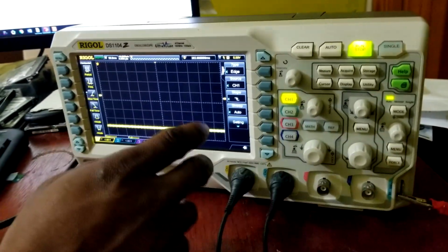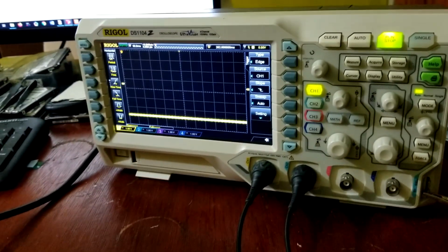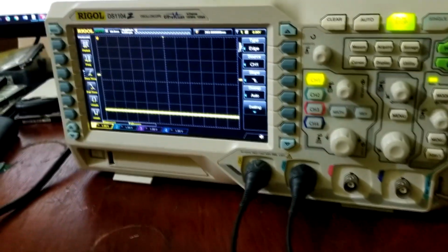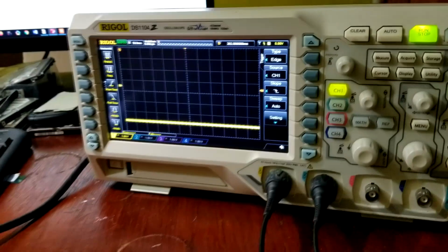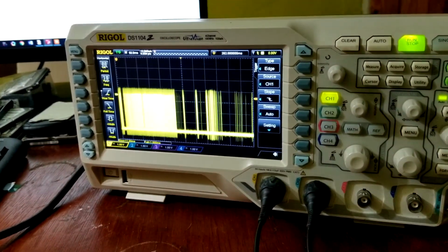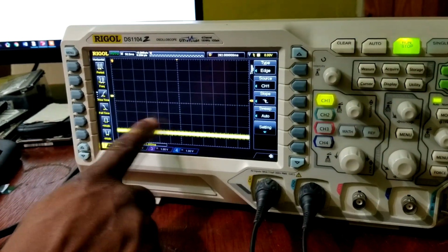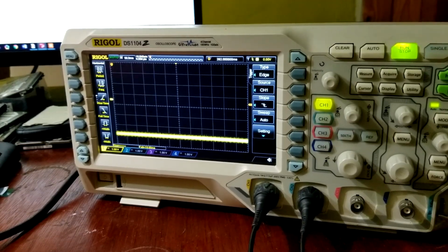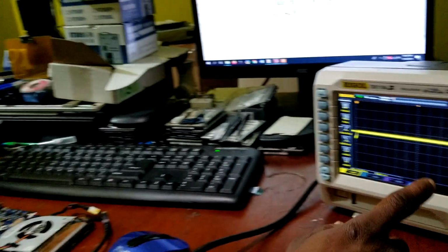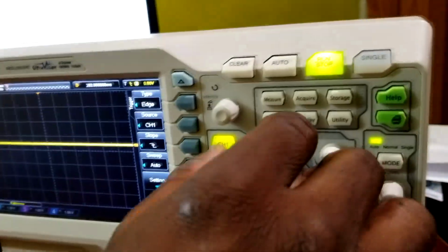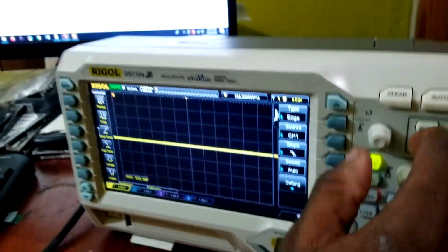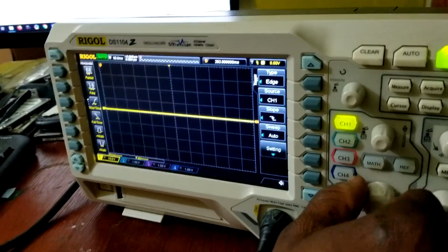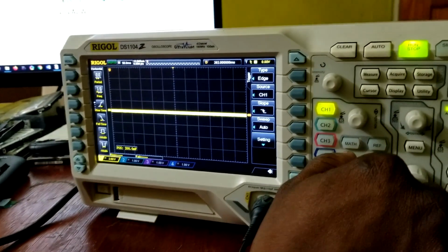And we're going to turn on the board. Let's see, watch the screen as I press the power button. This is chip select. See? BIOS is being read, and then it goes away. So that's a perfect way we can know that the BIOS has been read. All right, so let's set this back to 0 volts, right? And we'll set this back to 1 volt.